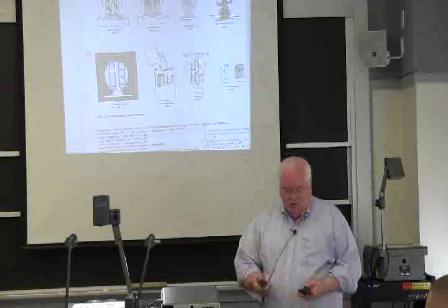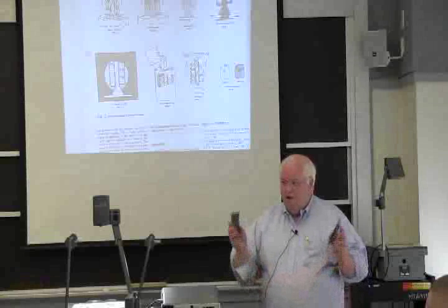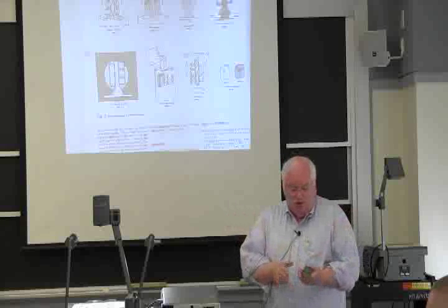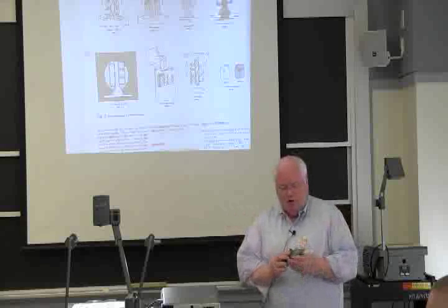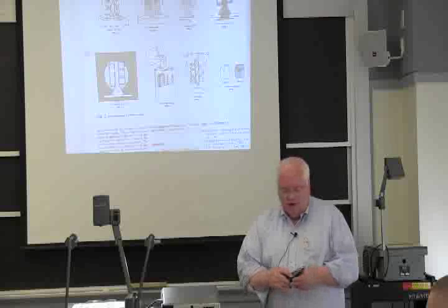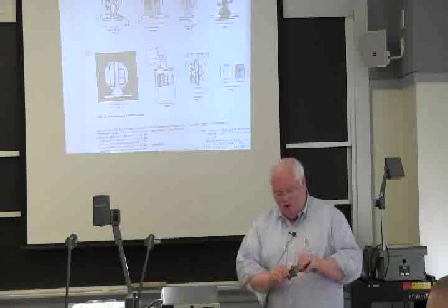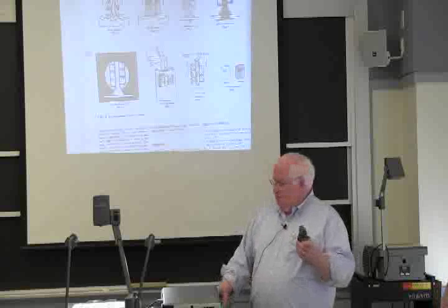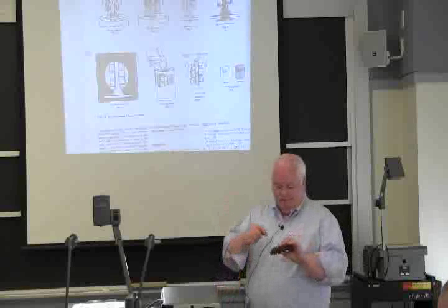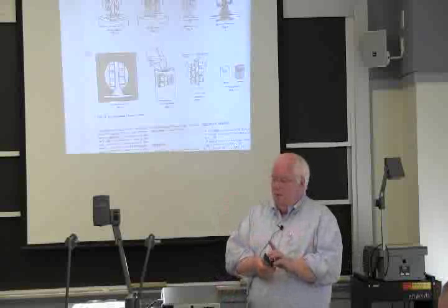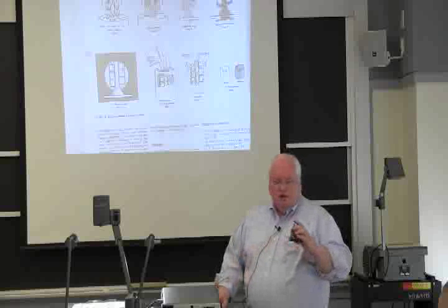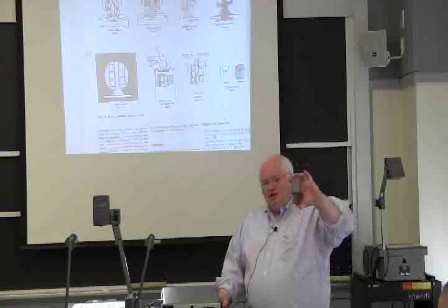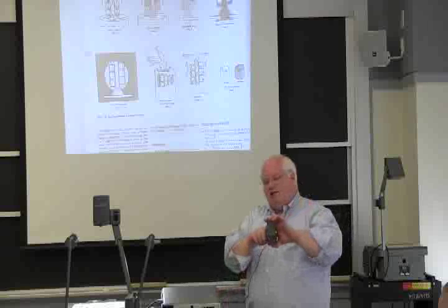And when they do it, they actually have a little ceramic mold that has the shape of the inside of this thing. So how would you make something with an internal cavity? This one's been cut in two, okay? So you can see the inside. But when Pratt & Whitney would have sold this, it would have been a solid part like this. They make it by the investment casting technology, and they end up with a polycrystalline grain.